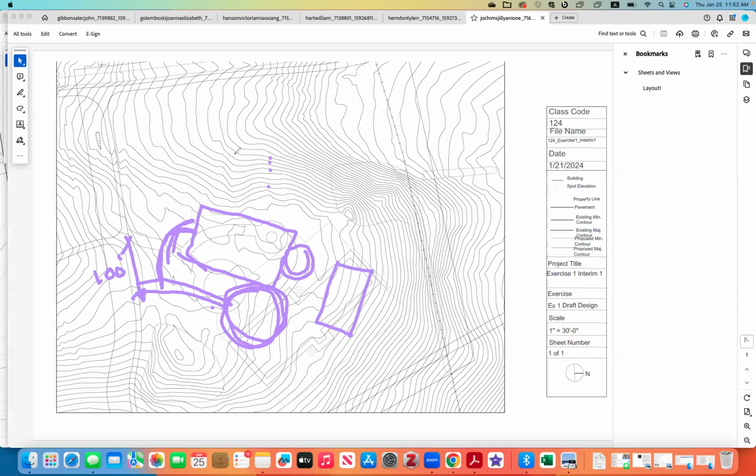So the first thing I would recommend is actually lay out your parking space correctly. Okay, the right dimensions, 65 foot wide and probably 40 foot, yeah, 40 by 65 would be the dimension that covers 10 parking spaces per row.